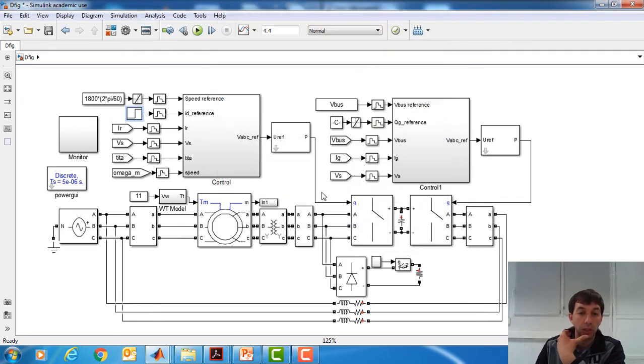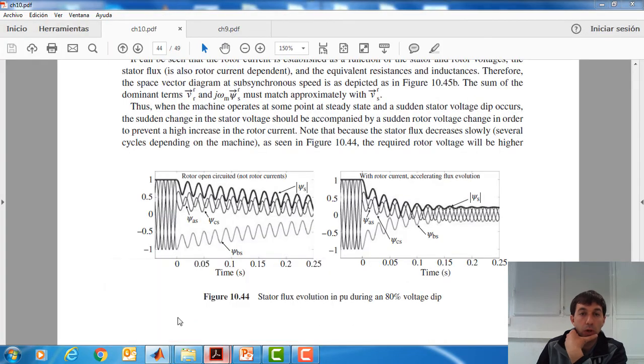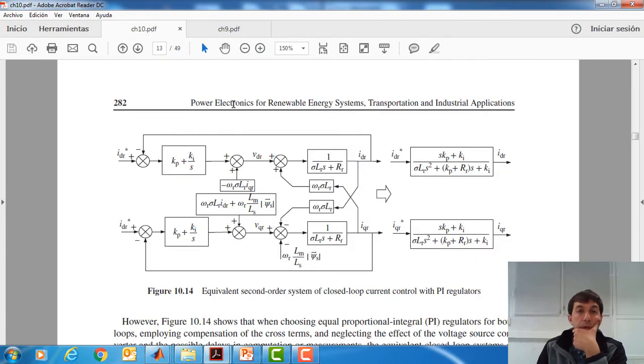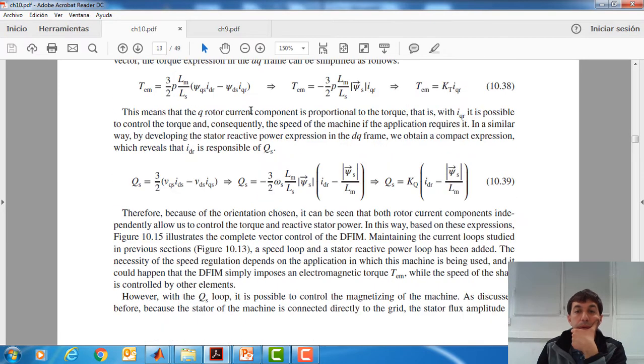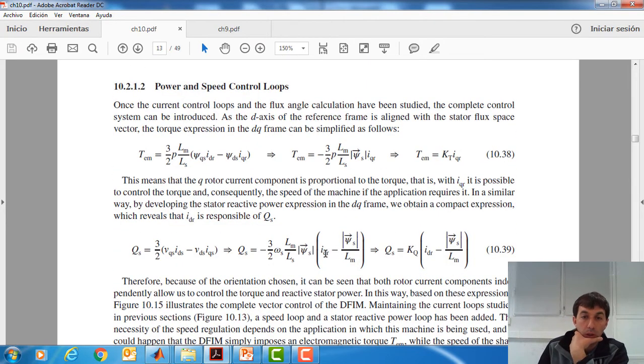of current. What means, if we go to this, and if I'm not wrong, to page 13, yes, to page 13. If we check this formula, we are providing as much current as we can here. Therefore, if we put this value in positive with this negative value, we are providing reactive power in negative value as demanded by the grid codes.